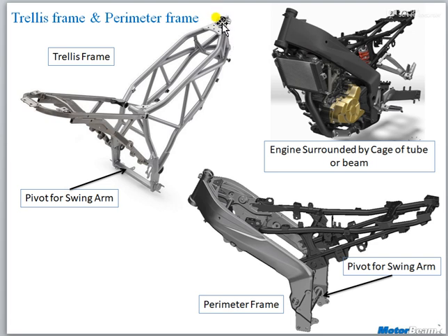From the head tube two members are going downwards. If you have a look, there is no main tube. The main tube and the down tube are combined together and become a thickened, high width member. If we treat the upper member as the main tube and the lower member as the down tube, then by joining those two we get one high rigidity member, a combination of a big member.